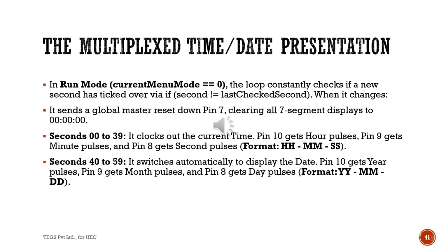Seconds from 40 to 59: it switches automatically to display the date. Pin 10 gets the year pulses. Pin 9 gets month pulses. Pin 8 gets day pulses.